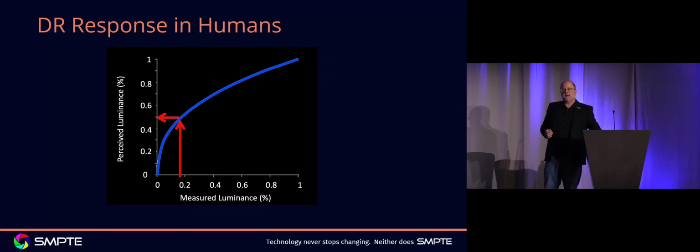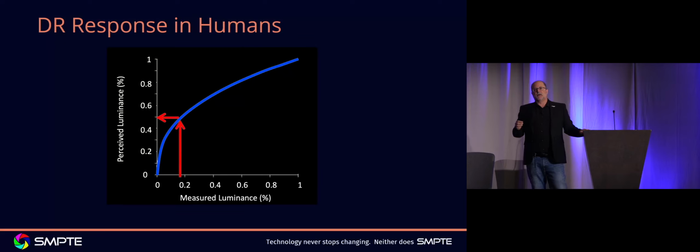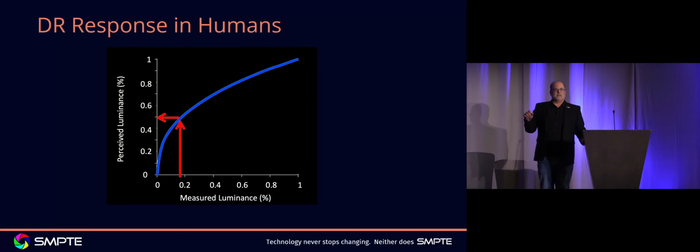Like I said, we're in a digital world, so we have to take those analog current measurements and give them a discrete value. That is a process called quantizing, basically giving it a defined quantity. You can think of it as a histogram. You have different code values, and each code value has a certain range. From this many millivolts to this many millivolts is this code value. So you have to give it boundaries because in a digital world, we work with ones and zeros.